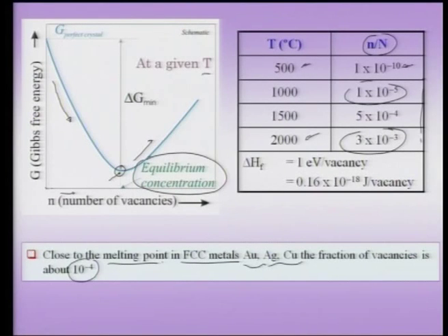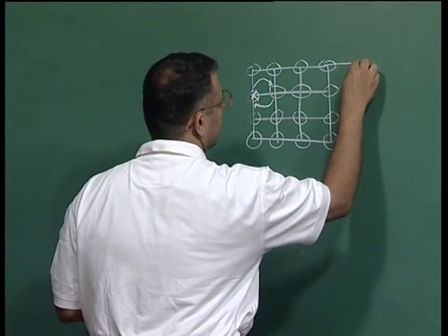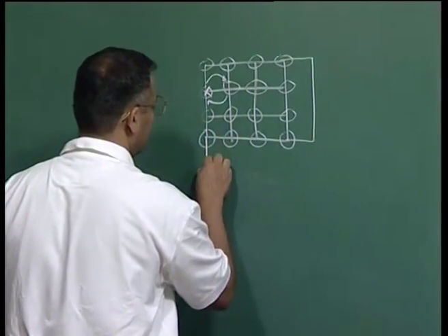This is something which we all know, but there is a more subtle and entropic reason why a metal would expand, which is what we have just seen: as we heat a metal, more and more vacancies are being accommodated into the material. How are these vacancies accommodated? Let me enlarge this crystal a little bit and draw a few more atoms.